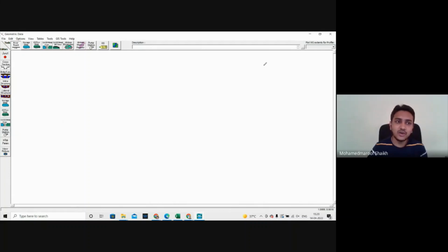When we are drawing the river reach, we start with a single click, and it is just a schematic diagram. So it may be straight, otherwise we can also give the shape exactly like the actual one. Here we assume that our shape is straight. No matter, it is just a schematic diagram. So start with a single click, and here I am ending with a double click.